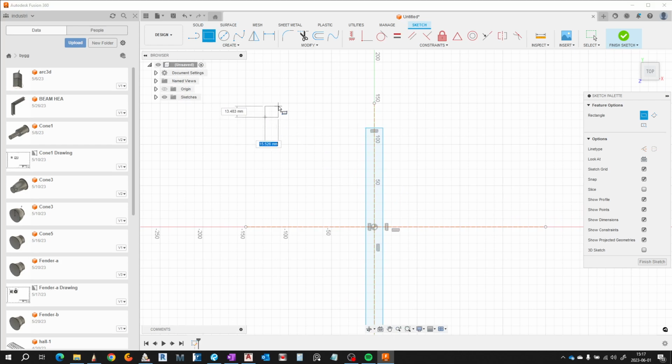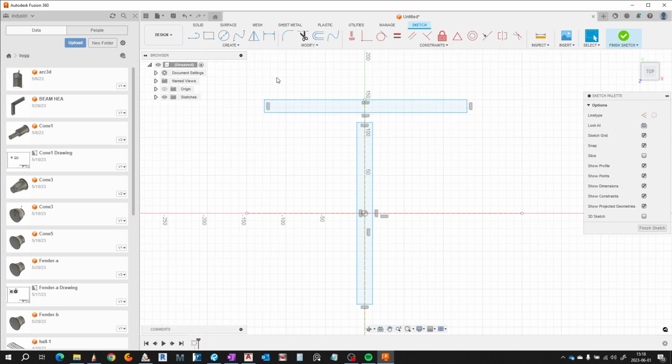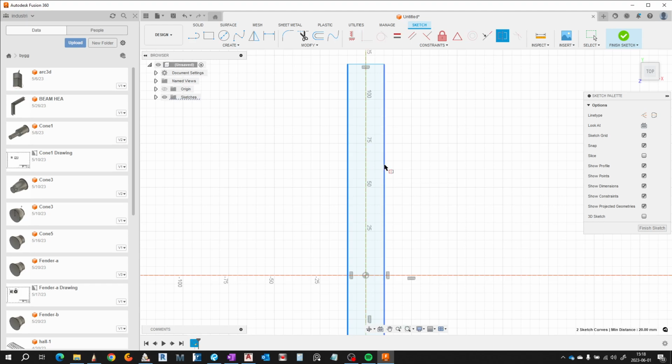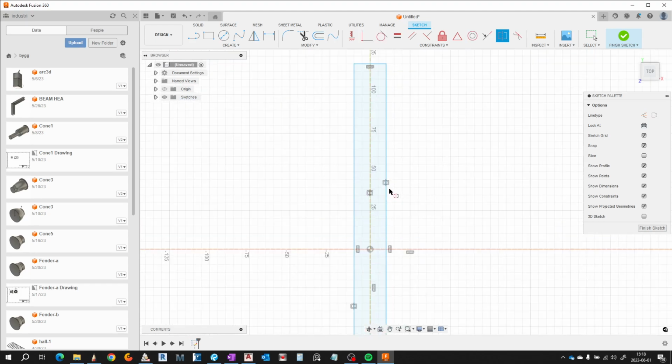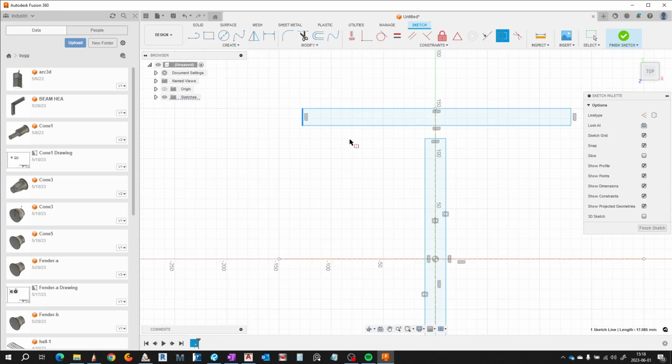And for the flange, of course, another. It could be that one. Right. We are going to use some kind of constraints because this is parametric software. So we're going to develop parametric objects. The constraint would be a symmetry. We need symmetry for this web, and you see the constraint here. We need a symmetry constraint for the flange as well.